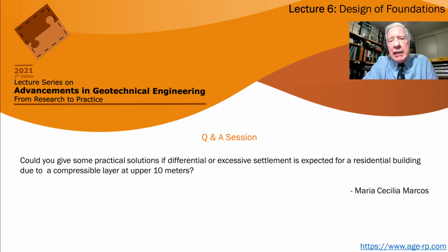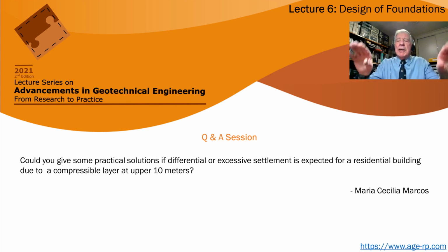You can do smart engineering and, to a limited extent, perhaps remove some of the soil and replace it with the structure so that you have a partially floating foundation. But the simple solution is probably to use piers that go through that softer layer onto the stiffer bearing stratum.